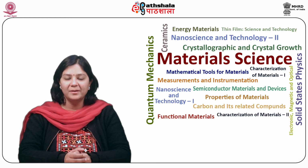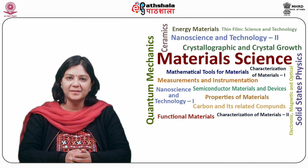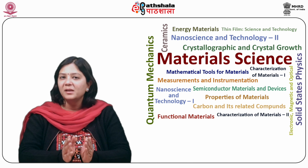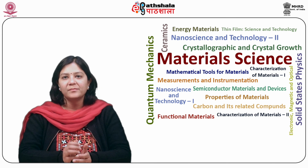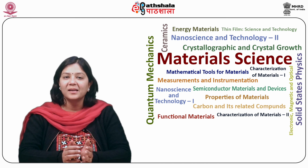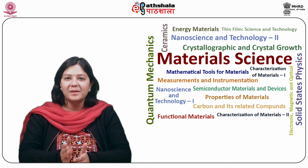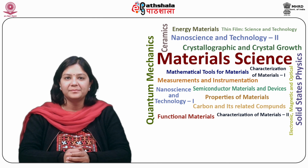Volmer and Weber predicted that if the adhesion between the substrate and the depositing crystal is weak, only 3D nuclei can be formed on the substrate. The internal strain in these crystals depends upon the lattice mismatch and can be high or low. This approach of epitaxial crystal growth is termed the Volmer-Weber mechanism.